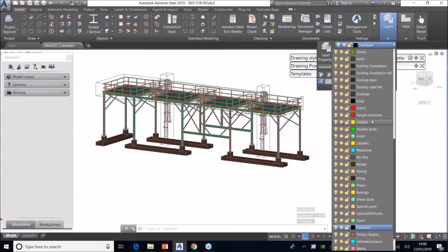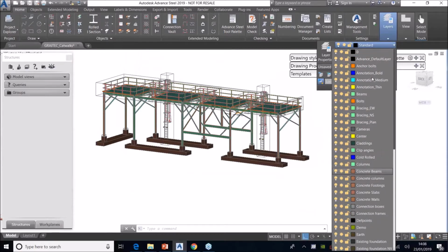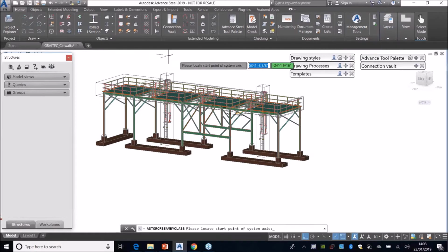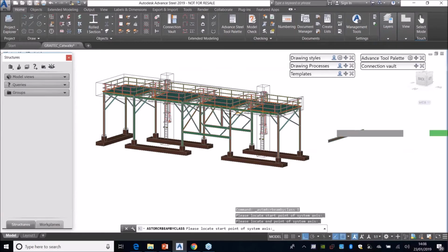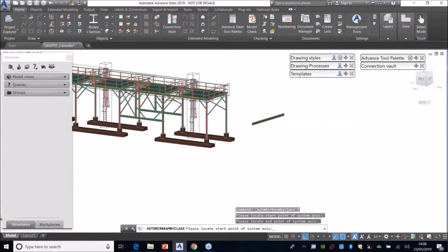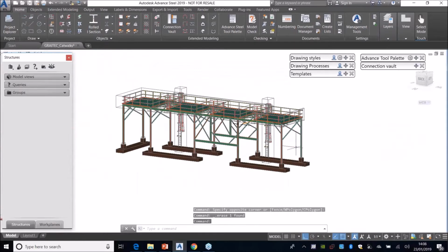Now, in this particular file, I've removed all the standard Advanced Steel layers, okay? So there's going to be minimal mapping when utilizing specific functions. For example, here, if I create a new section, it will map. I do have a beam color layer in there. However, not all objects like grating and so on will map to original colors, and maybe these line types will need to be named in a specific way to follow their particular standards, okay?